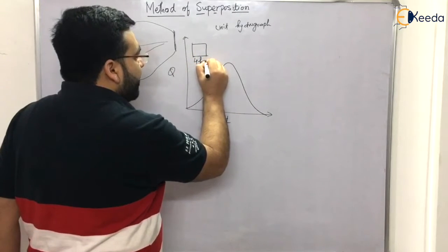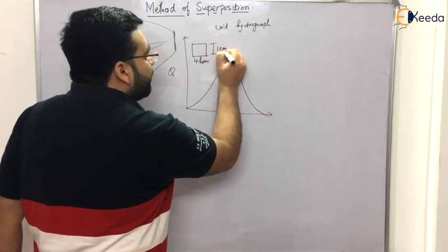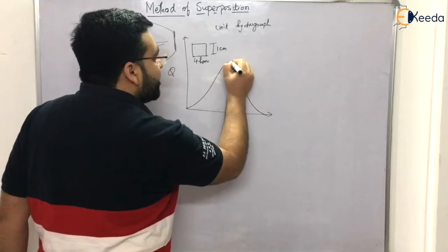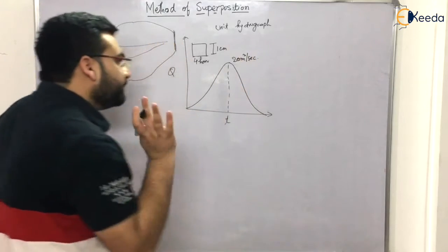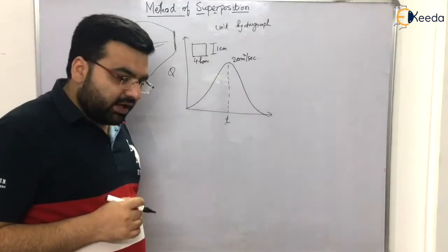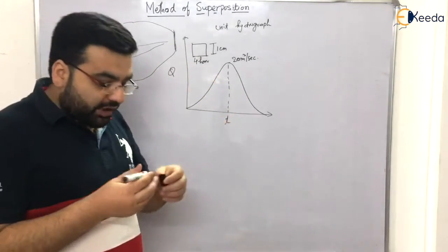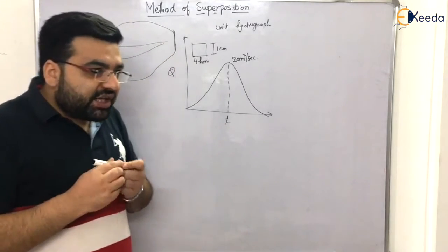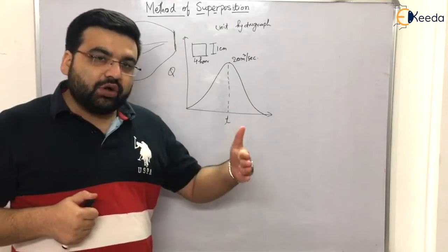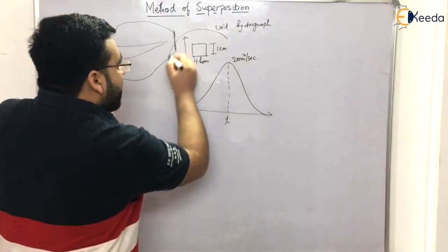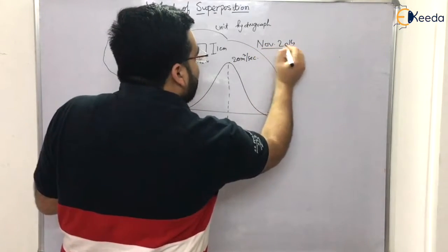You have taken a unit hydrograph of 4 hours duration, and unit hydrograph means it has a depth of 1 centimeter, and let us say it has a peak discharge of 20 meter cube per second. This is what we have got. But this is a 4-hour unit hydrograph for a particular storm which lasted for 4 hours. Let us say you recorded this data in November 2014.